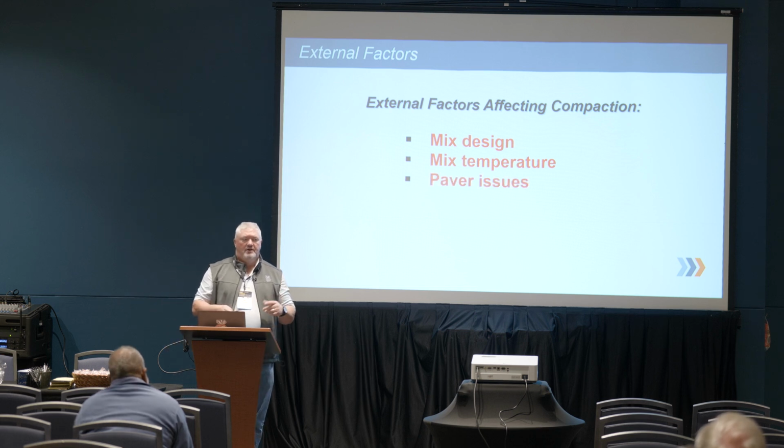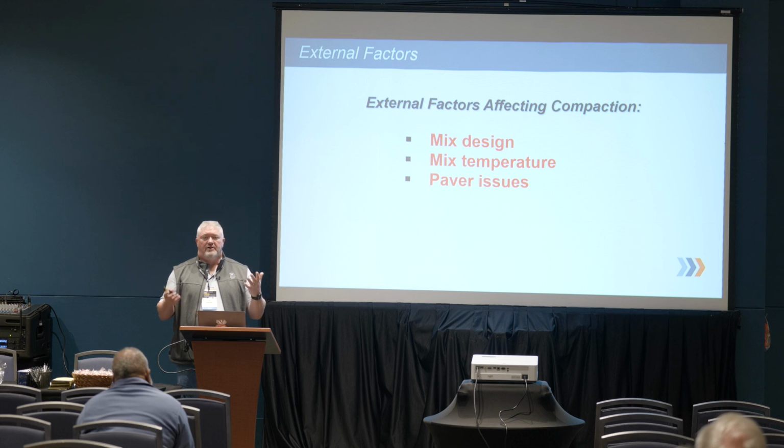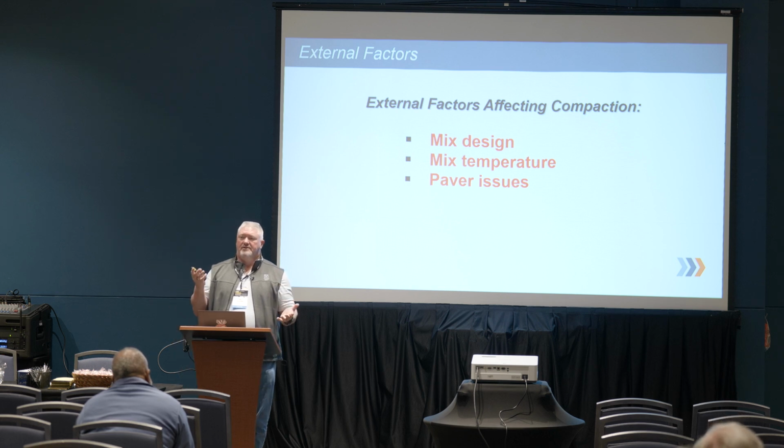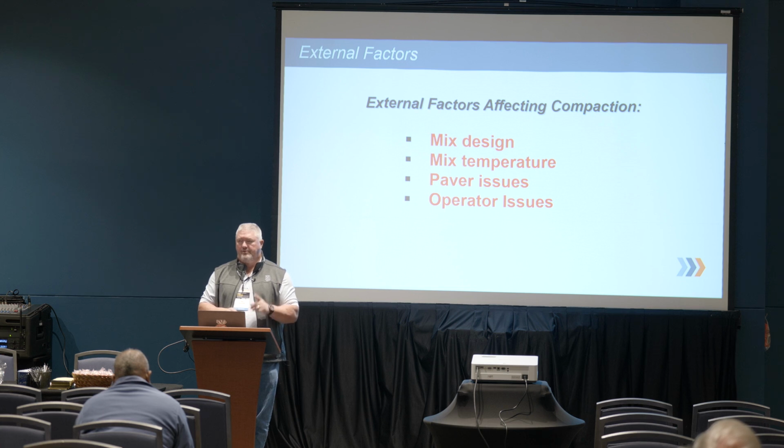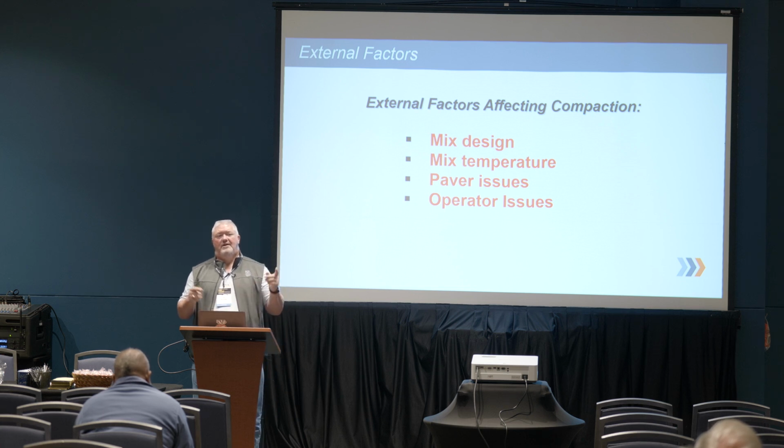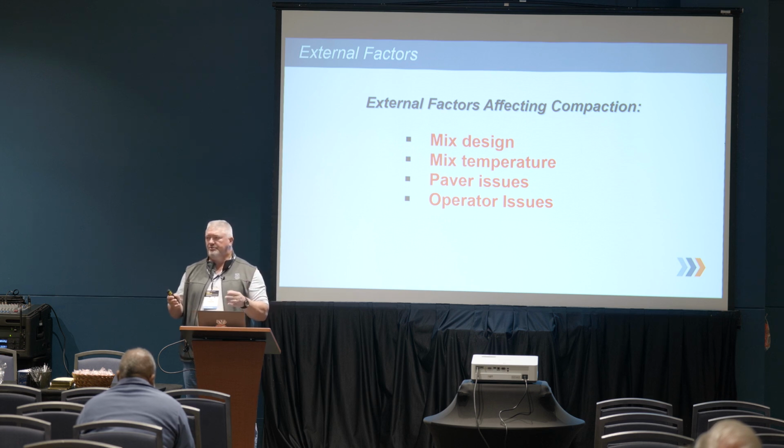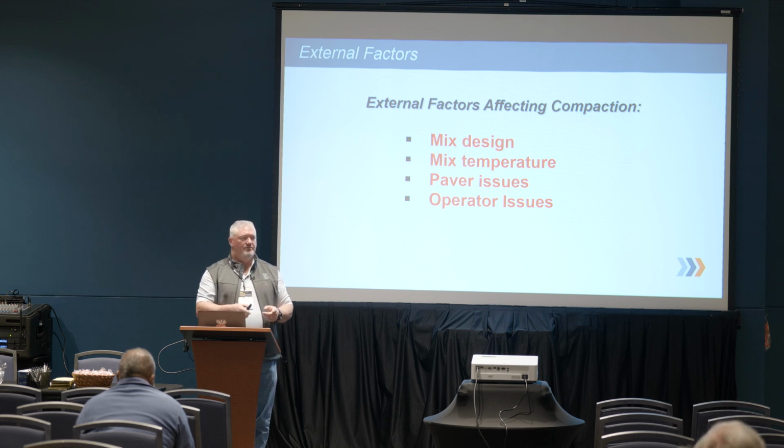Everything needs to stay consistent. Paver issues. If our screed is not set up properly, there are some things that we can't fix with the roller that the screed actually puts in there. Understanding the equipment, the proper setup is key. Operator issues. This is one I always say: when I go on a job site and I'm showing someone how to use a machine, before I leave, I want them to understand the full functionality of that machine like I would, and the adjustments they need to make and why or how they're making them.